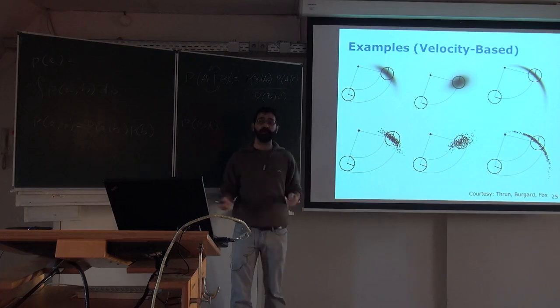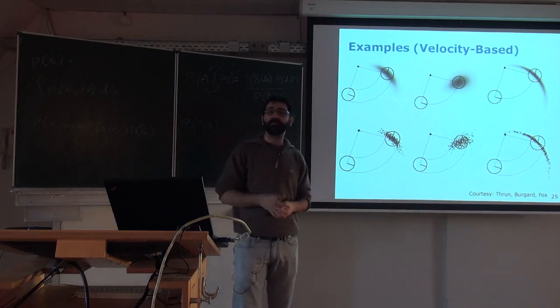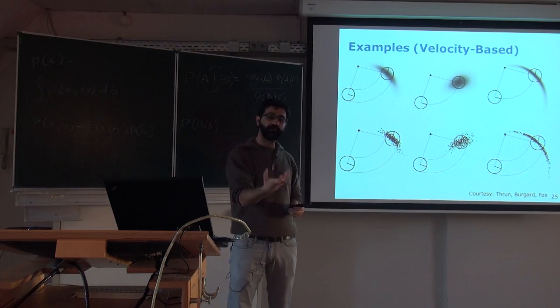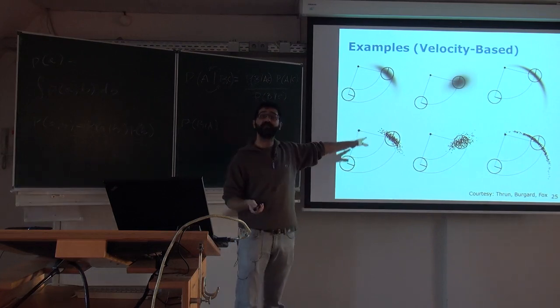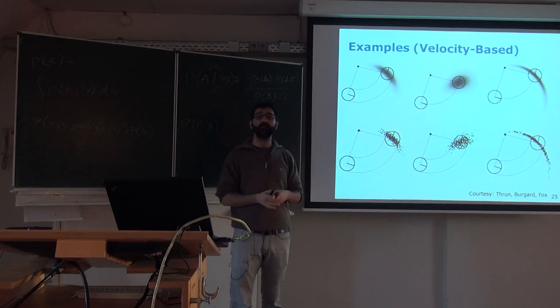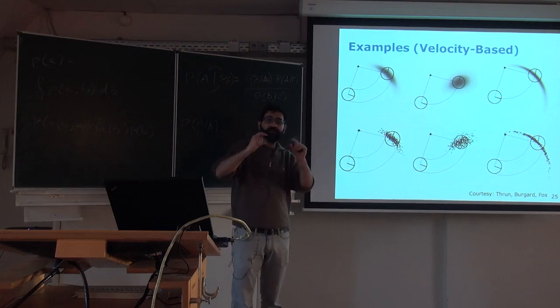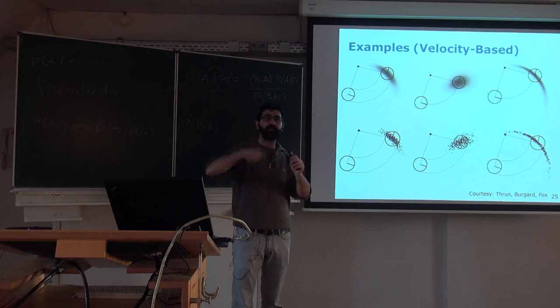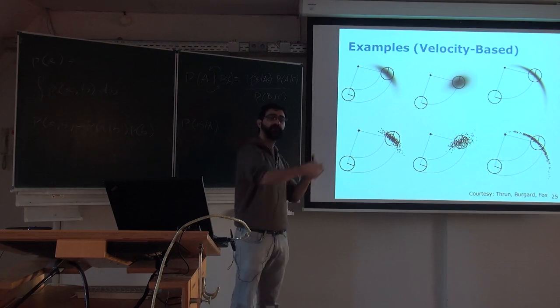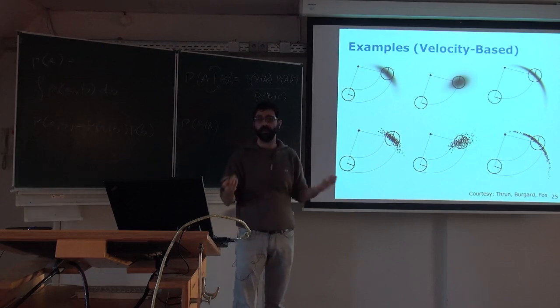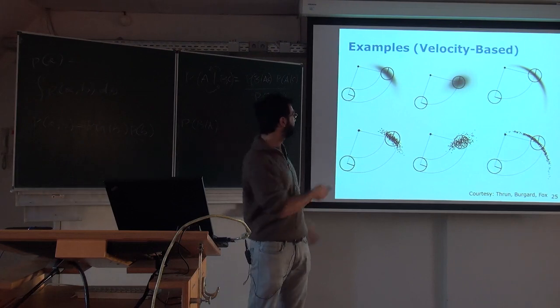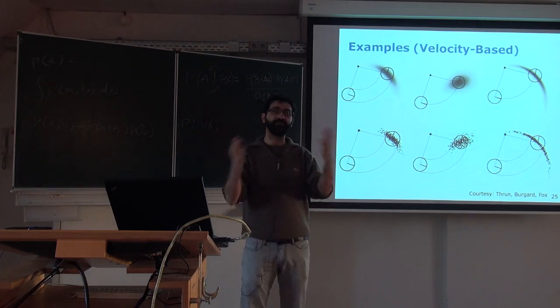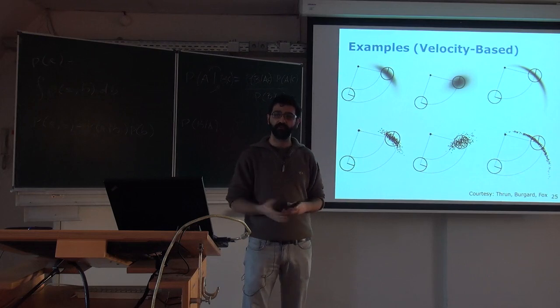Okay, so the effect is the same, and actually at the end what the robot does when it gives you an odometry is implementing these things inside. Okay, because somehow the only thing you can measure is the incremental displacement of the wheels, and it translates it into velocity of the wheels, and then it integrates over time to get the real position of the robot. Okay, so at the end it's good that they somehow represent the same distributions. Okay.